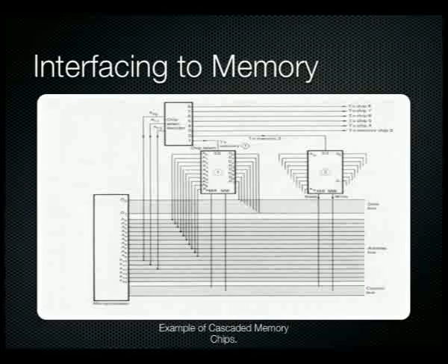We pump it through a decoder, and the decoder can simply activate one of the 8 lines, and each line goes to the chip enable or chip select of one of our chips, which then turns that chip on. So when you give it a particular address, only one of the chips will turn on.